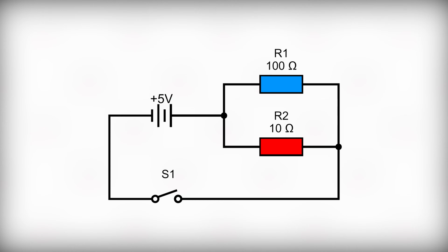Which resistor do you think current will flow through after we close switch S1? If we follow the above statement, it's the R2, because its resistance is 10 times lower than the R1. And this answer is, of course, incorrect. The current will flow through both resistors, but it will be distributed in inverse proportion to their resistances. And it's very easy to calculate.